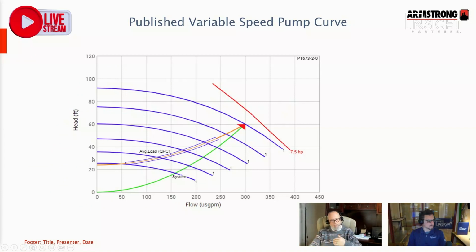If you use an Armstrong pump with sensorless control, where we don't need a sensor out in the building automation system, we use the Affinity laws, speed, power, and flow, to determine where that pump is running at any point on its curve. We base it on a 40% minimum and calculate out that quadratic pump curve, and that's what controls the speed of the pump, based on system differential parameters, as valves open and close and change the head losses in the system.